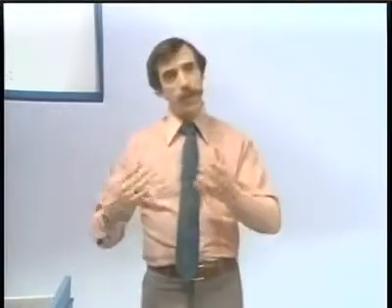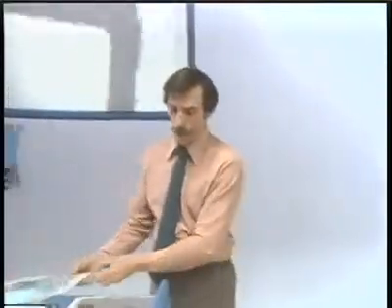Okay, well, so what we've done so far for continuous time and discrete time is to talk about modulation, amplitude modulation, with complex exponential and sinusoidal carriers. We saw that the analysis is very similar, although applications are slightly different. And now what I'd like to turn to is a different choice of carrier signal. And the carrier signal in this particular case is a pulse train rather than a sinusoidal signal.